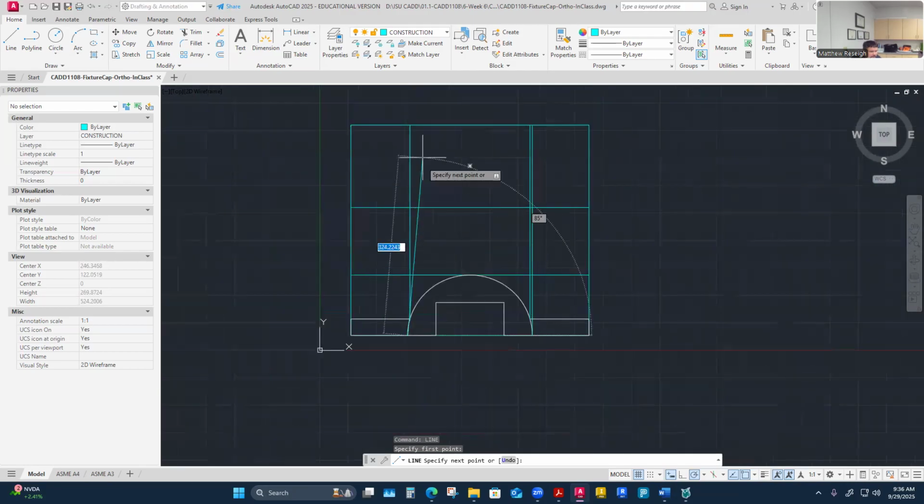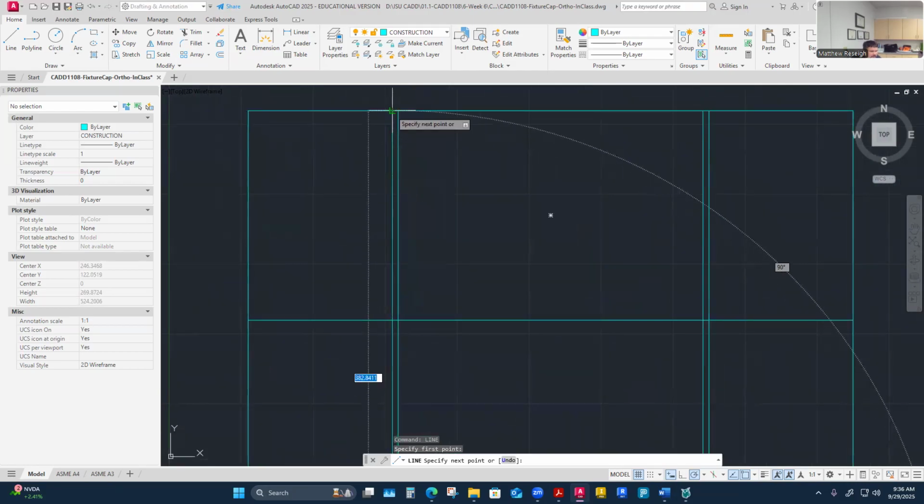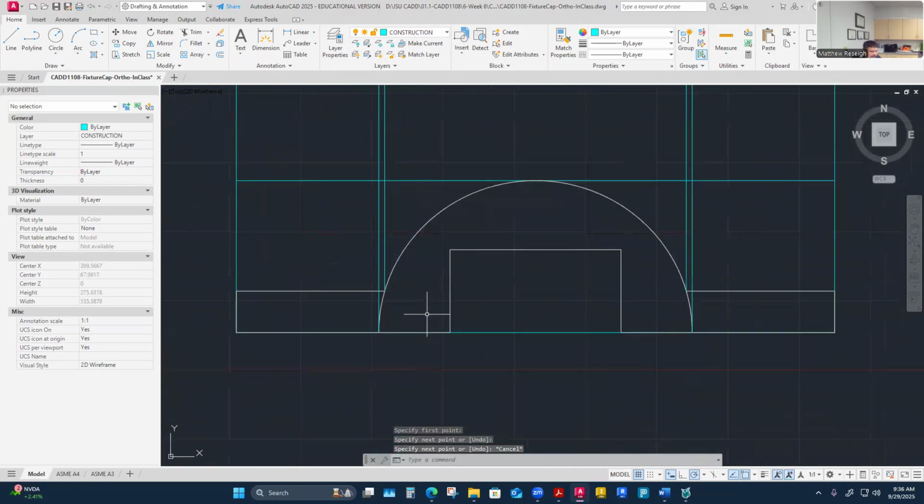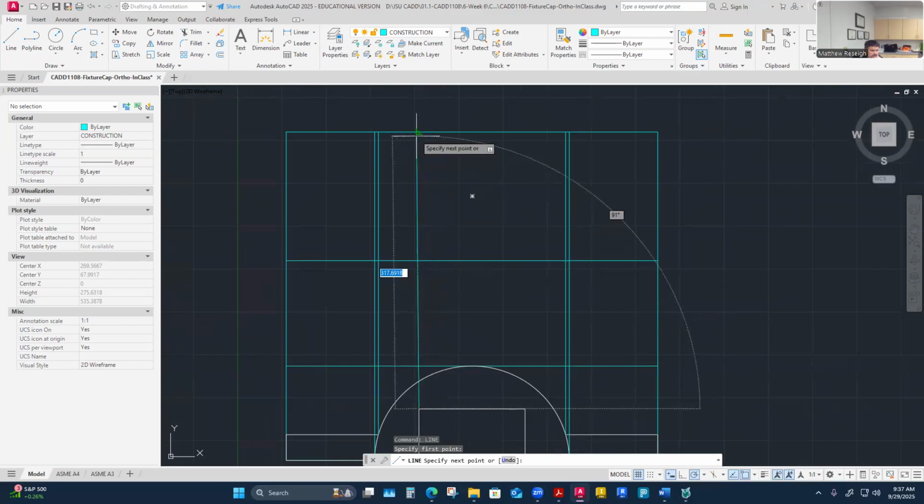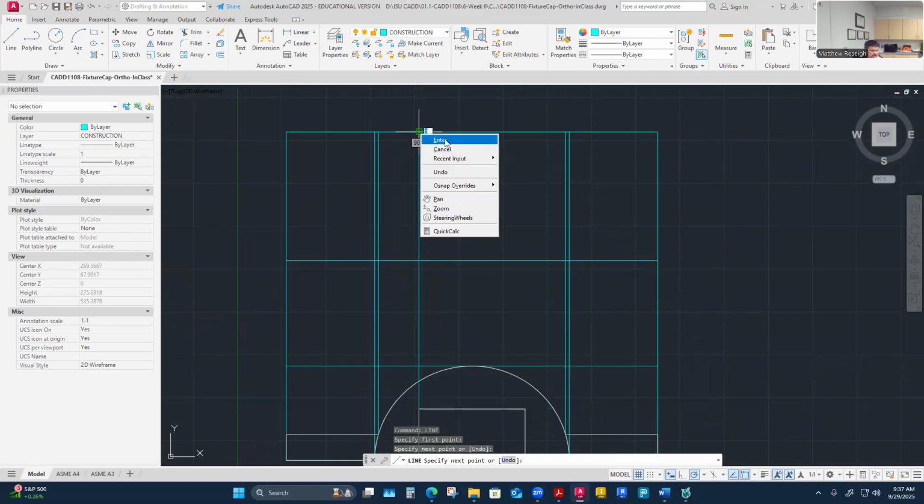The bottom of that ear where it meets the radius is probably what I'm going to visibly see, and this other would be more hidden there. And initially, when I started this, I wondered if my imagery showed a hidden line there or not. So I'll look, and then I think the only other thing I'm really going to project up is this little slot width that's cut out. So a few projections.